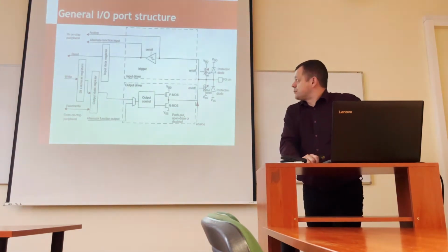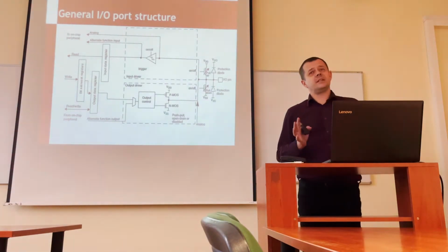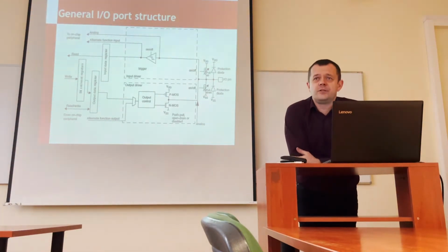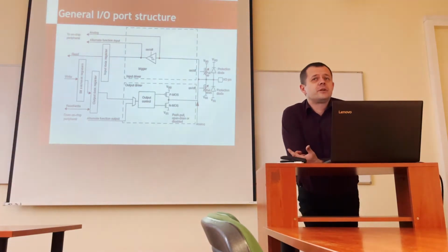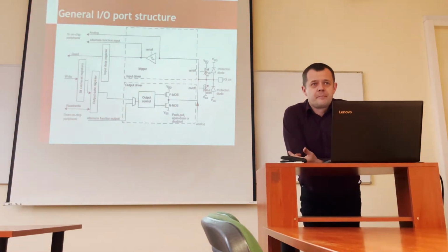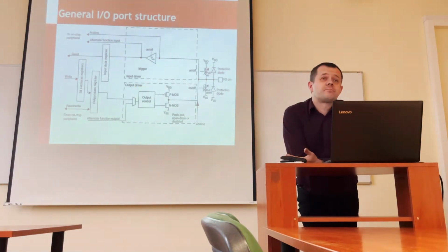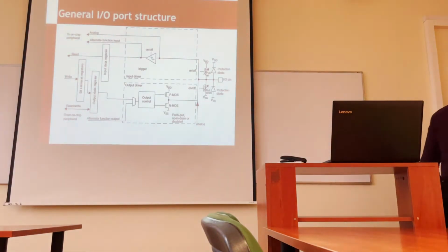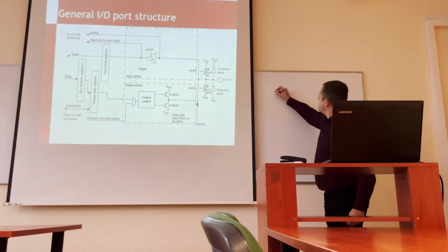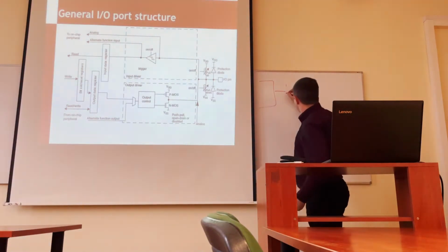inputs to one output. What does this 10 milliamps give us? It's still a pretty decent current if we want to connect some load. From a practical point of view, for example, you can connect an LED directly. You can try to drive a relay switch out of it. From the microcontroller point of view, there is no problem.